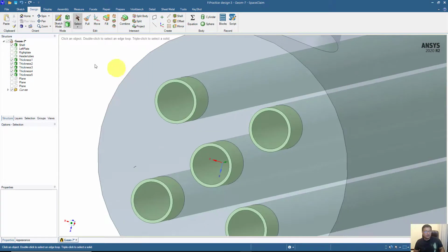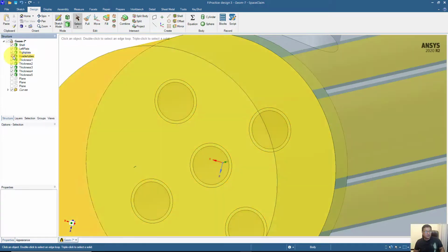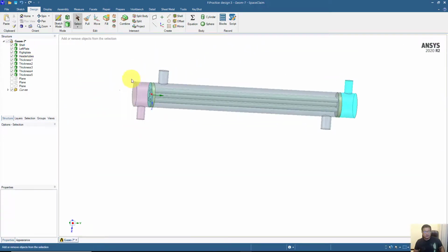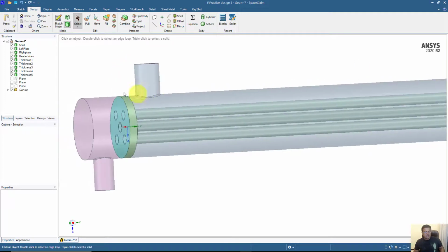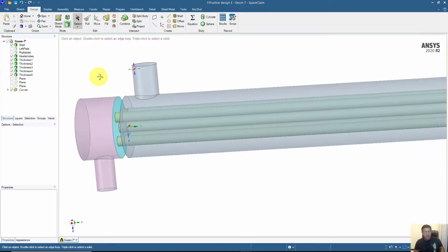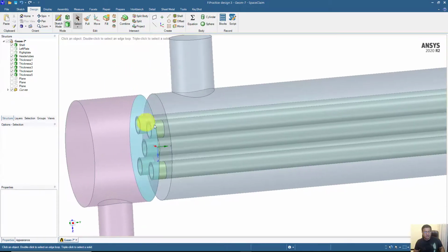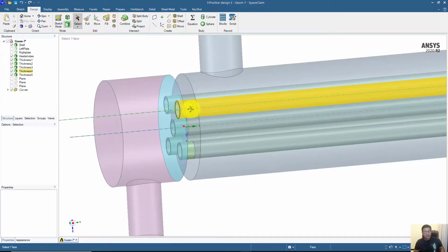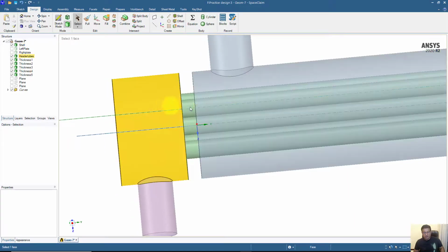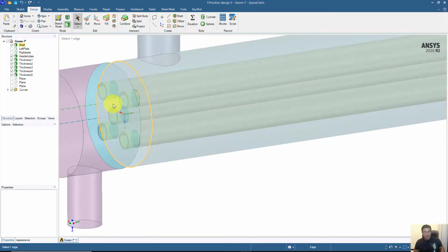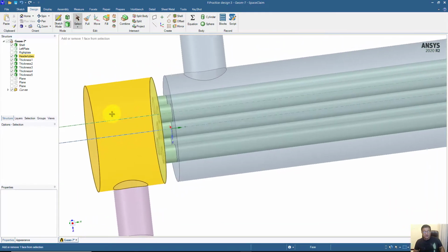Now we can display all these parts in one go. So we have the different volumes, and these two plates will not play any role in the CFD analysis, so you just have to create the interfaces, and maybe we need to split these surfaces for making the proper interfaces between these sides. But at the moment they are almost done for the CFD analysis.